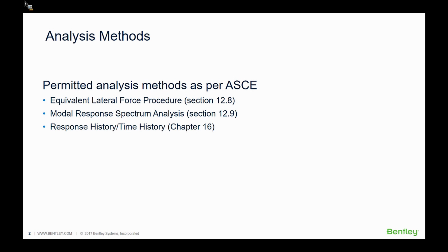The fact that it's a static analysis means it is easier for us to do hand calculations if required for quick verification, and results are also much easier to comprehend. However, one thing to keep in mind is that although the equivalent lateral force procedure is a simple analysis method, it is not universally applicable under all scenarios, and we will discuss that more in our next slide.